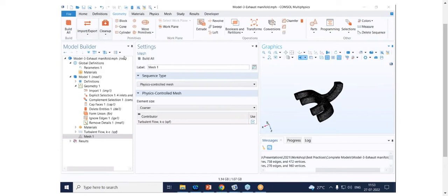So there is a question regarding why the mesh is getting overlapped in the case of form assembly. So yes, as I was talking about, the form assembly provides the flexibility to the user to apply the boundary condition as per your requirement. And due to this flexibility, the meshing requirement is also different, and that's why the overlapping here you can observe.